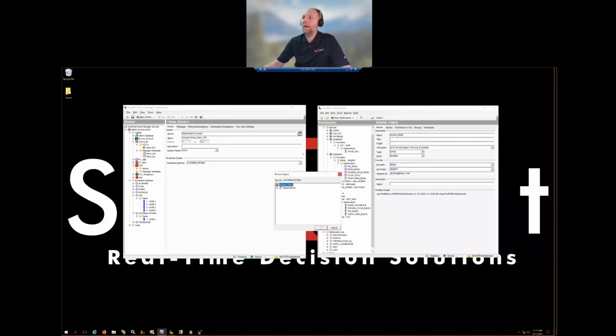If we go ahead and click on the Browse button, maybe we're interested in every alarm under line 01A. I can go ahead and select that level and pay close attention to the pattern match as well as the alarm and group itself. And you'll notice that we insert the correct variables or wildcards and we switch to simple pattern matching in order to create a one-to-many relationship. So this one alarm that you save in FirstPage Alarm Manager can match tens or hundreds of alarms or even thousands of alarms in system platform. Once again, with the only goal to reduce configuration for the end user.